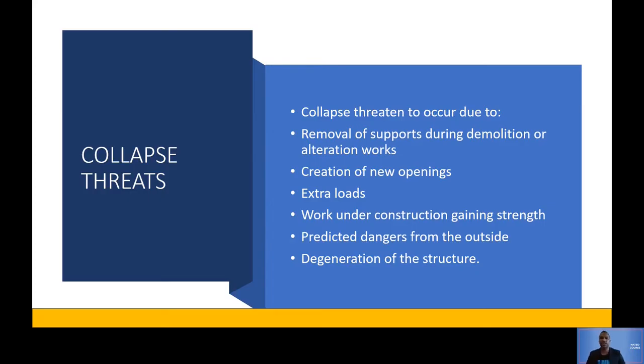And then creation of new openings. If you're putting a new opening in your building, then you do need to put in shoring. Extra loads: if you're going to add extra loads on the building, such as another floor, then you need shoring. Work under construction, gaining strength.